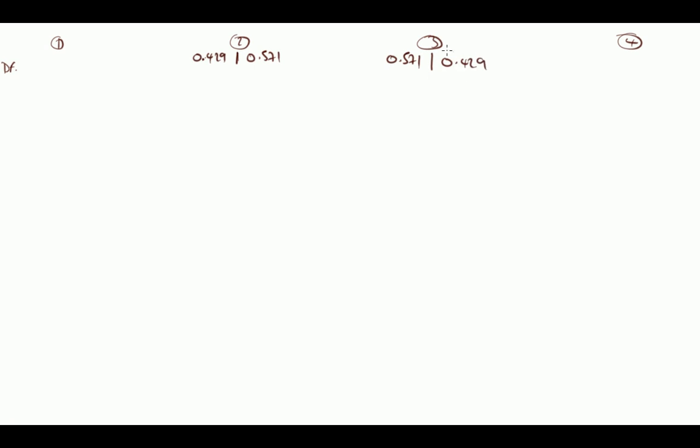Those will always add up to 1 around a joint. If they don't, you've done something wrong. And they are derived from the ratios of the stiffnesses, if you remember.